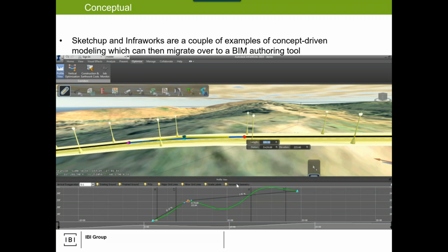If I'm doing a building, I would prefer Arc, Struct, and MEP to either be all in EcoSim, all in Revit, all in ArchiCAD, etc., and then use analytical tools like Tekla to push into fabrication, or Robot, or whatever the required analytical tool would be, but at least the building model is wholeheartedly from a common point.